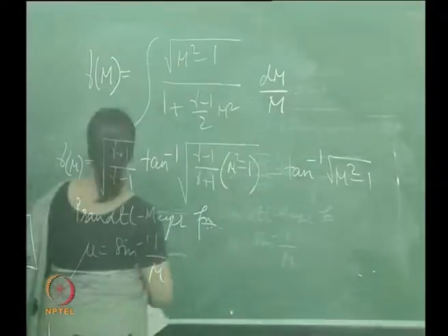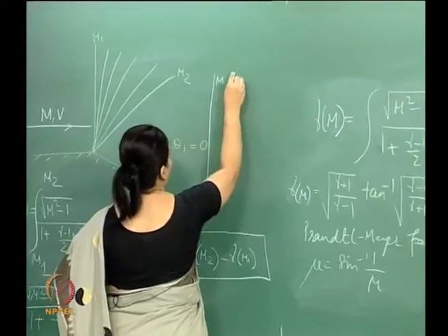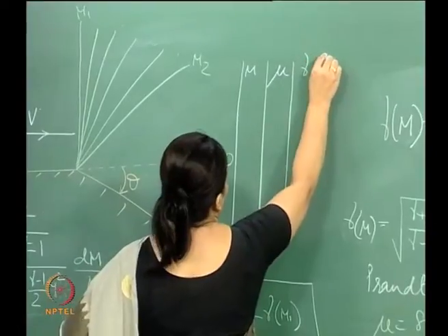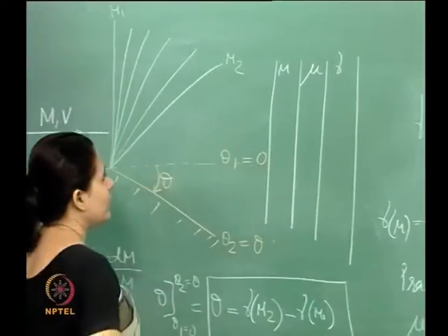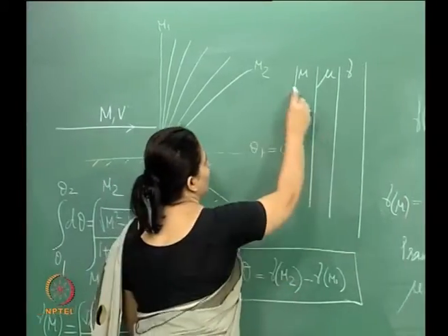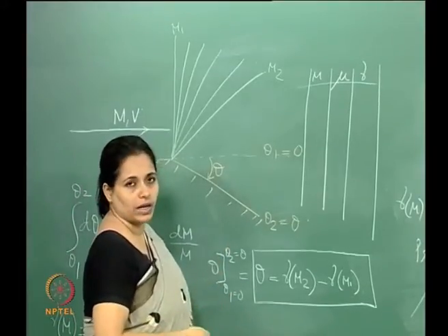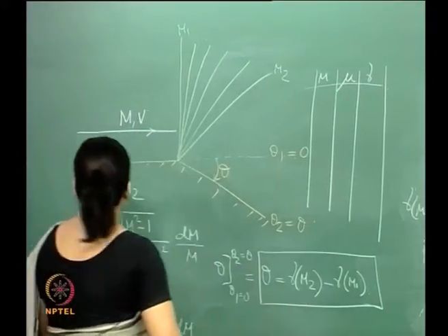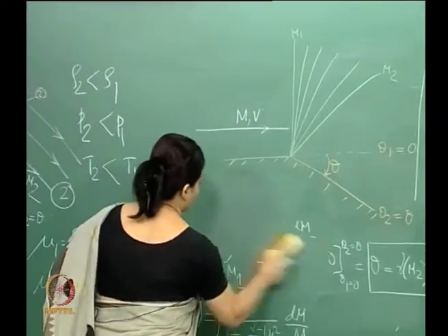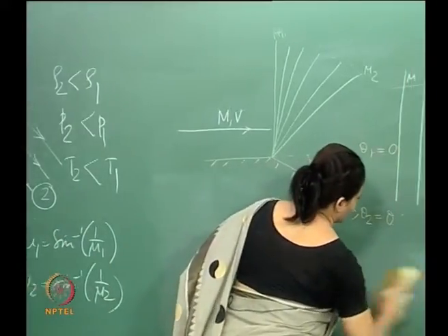What you will have in the standard charts is basically a listing of the Mach number, the Mach wave angle and the Prandtl-Meyer function, right. So, this is what you will have for the Prandtl-Meyer expansion waves. The standard chart will have the Mach number, corresponding Mach wave angle and the Prandtl-Meyer angle. Okay. So, let us therefore look at a problem and see how we can use this chart or what else you can use.